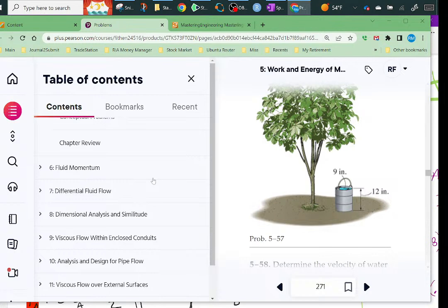What I mean by that is you're in your boat in the water out here, and you want to take a scale version, and maybe you could put it in some other fluid, like alcohol or something, so that the properties of the fluid would scale, and then the boat size would scale, but you don't get that. What you get is a thing called a Froude number and a Reynolds number, and it turns out they don't exactly match. It's hard, but they have figured out a way around this for how they scale their boats and run them down there. There's an extra complication when you're talking about ocean-going vehicles. Then you get into waves and stuff like that, which gets even more complicated.